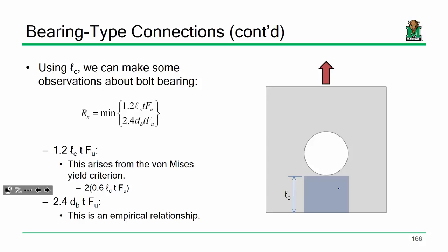So we go to somewhere like Huntington Steel, and we order a couple hundred different connections. We start varying bolt diameter and thickness and steel grade, and we start failing all of them. And then we record the stress, and we say, all right, can we match an equation that's simple and that works? And that's what you get down below. So that's an empirical relationship, okay? Again, it results from doing a lot of breaking things in the lab, but that's essentially the long and short of it. All right. Everybody good?